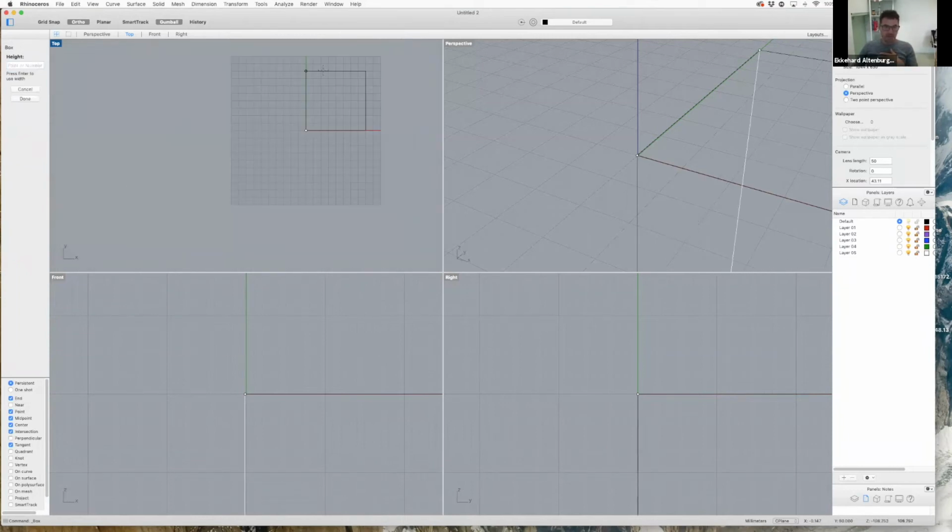And when you look, you already have your ground plate. Now we want to go into how high it is. We know we are cutting a 3mm thick plywood. So the height here, as suggested in this box on the corner, how high is your cutting material? It's 3. And then we press enter.